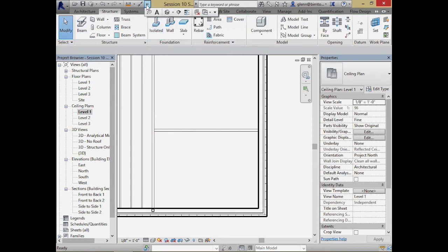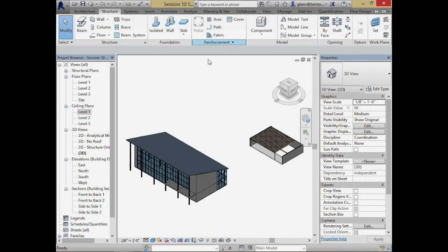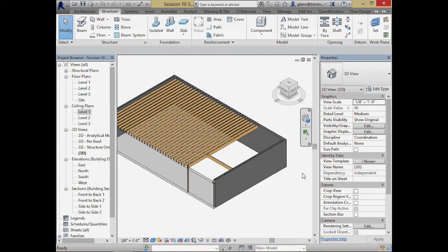So what's happening now is I have a lot of load being concentrated on a big old fat beam, and it is transferring to another big old fat beam, and then the load that's actually coming to that point in the wall is very concentrated, so it's probably going to be over 2,000 pounds.